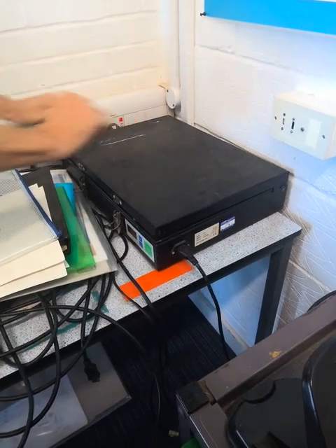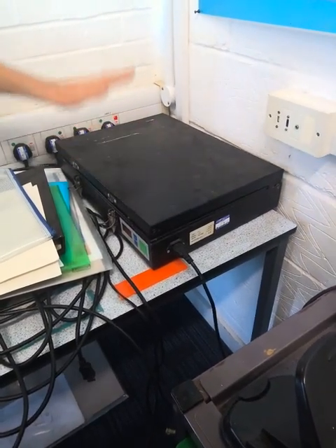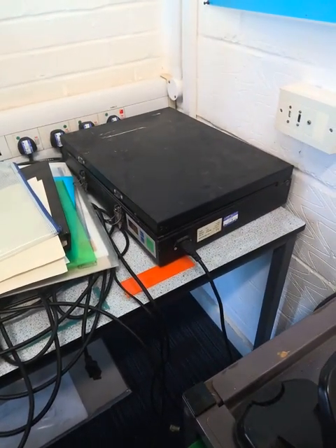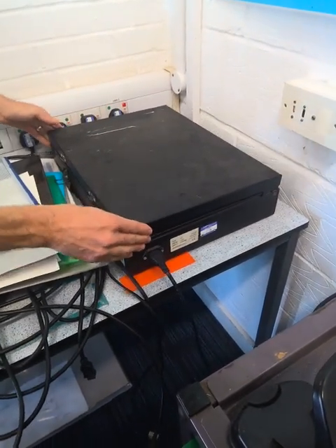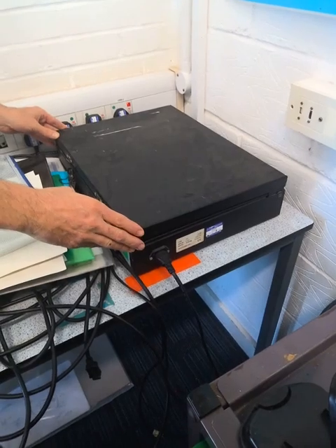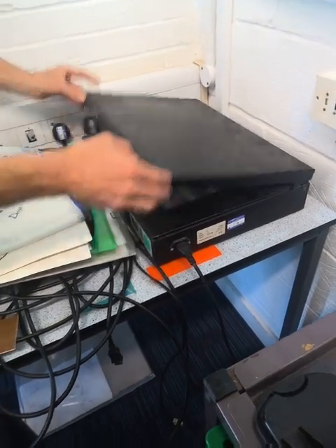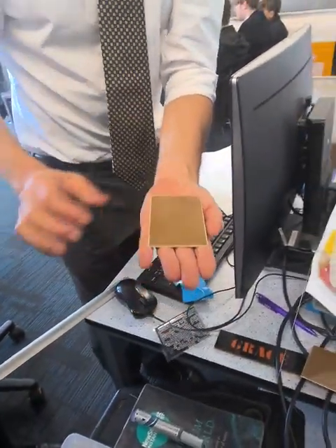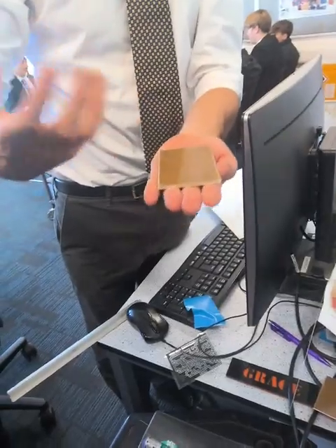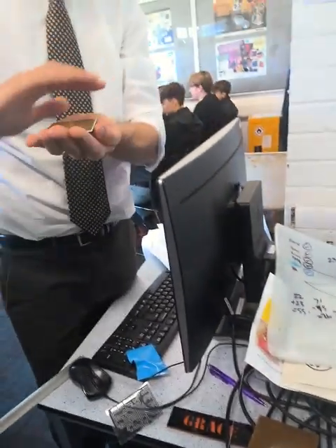You then put your mask in, you put your piece of PCB in, and then you do your 90 seconds, okay? So 90 seconds to develop your image onto your piece of PCB. Everyone understand? Right, once we've done that, we take this out. Often what I suggest you should do is put that onto your hand like that, so no more UV rays can get to it. We've had the UV from the box exposing it, but we don't want any more.